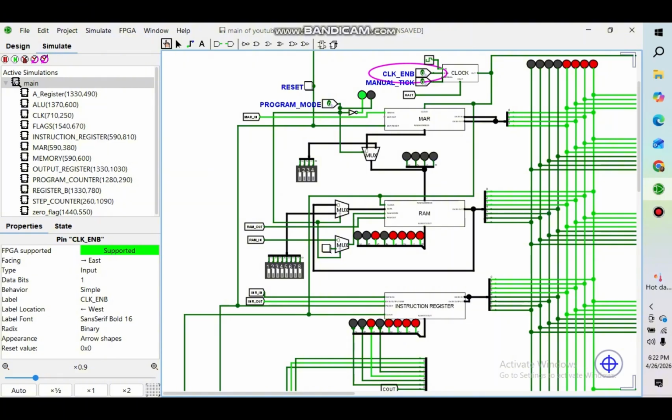The operand is only sent to the bus during the execution phase using a tri-state buffer. This ensures there are no bus conflicts during the fetch time. Now I will demonstrate the jump instructions.